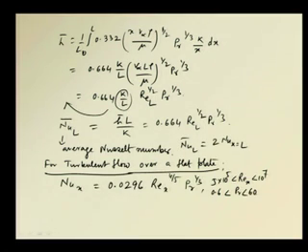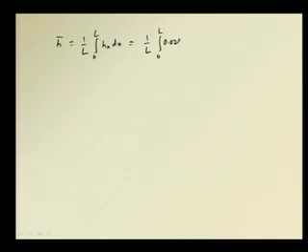Now, exactly in a similar way as we have seen in the previous case, if we do the integration, we can get the average Nusselt number in this case also. So, the average h bar will be 1 by L integral 0 to L Hx dx, and this will be equal to 1 by L integral 0 to L 0.0296 ReX to the power 4 by 5 into k by x into Prandtl to the power 1 by 3.